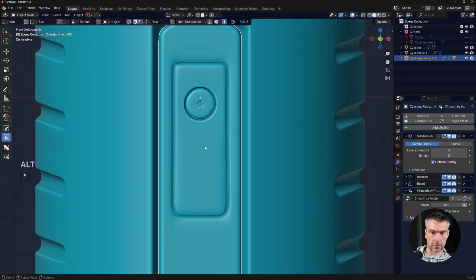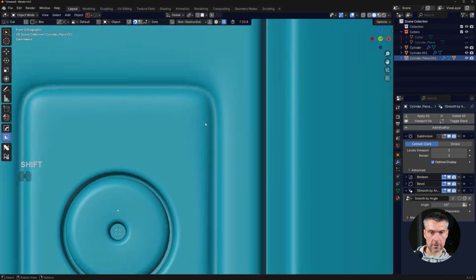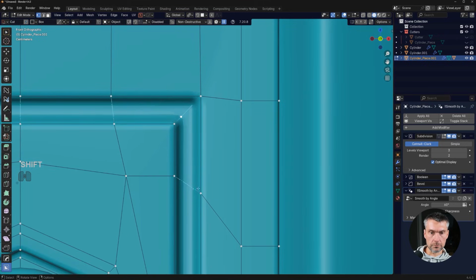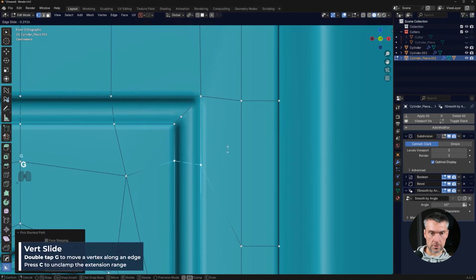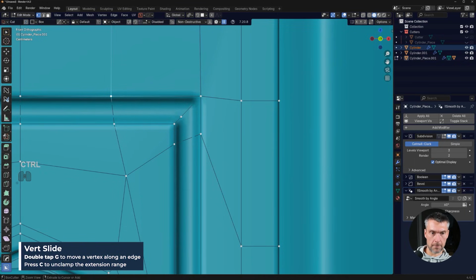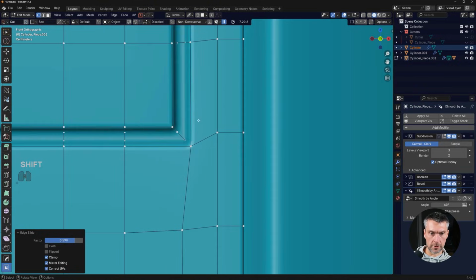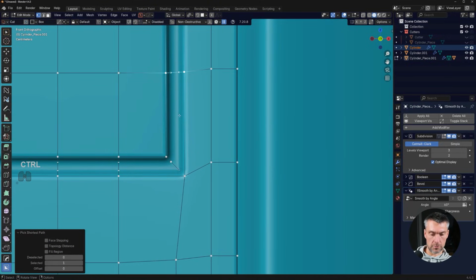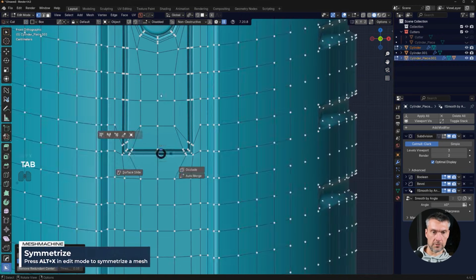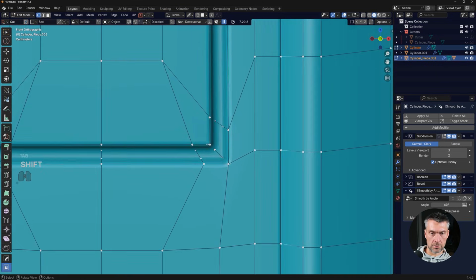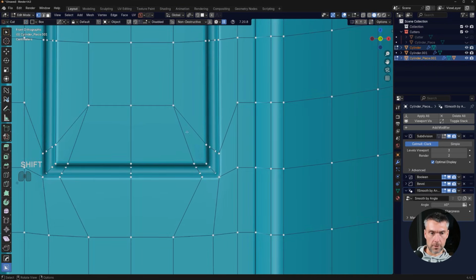And you're gonna get this kind of a shape here in the middle. And again, if you wanted to tighten the corners, you have to do the same trick, right? So just grab these and GG and tighten them up. And again, this is a flat surface, so we don't have to really worry too much about the curvature. Now this one should be dropped down, so GG here, and this one GG here. Mirror to the other side, and you're gonna have a tighter corner here. And in addition to this, we probably gonna have to run a loop here in the middle.